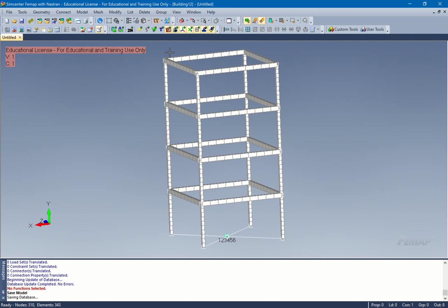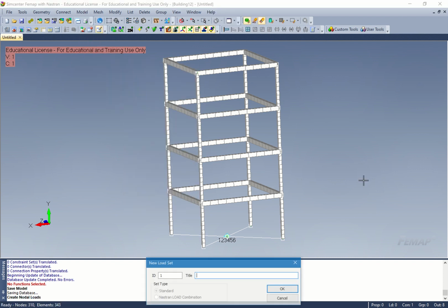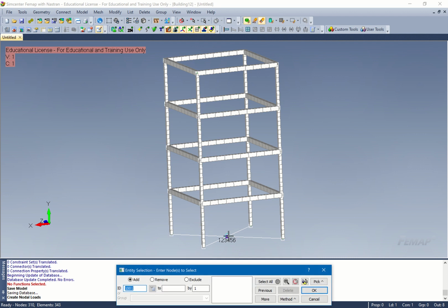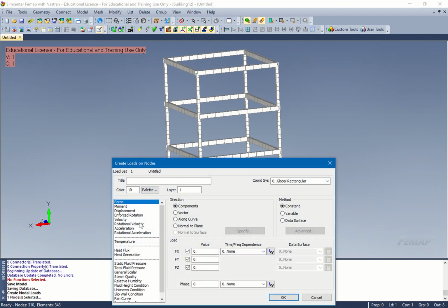So we're going to say model, load, nodal, and give it a name. Select that middle point, 1000. Perfect, that's 1000, not 1001, right? Now, this is in terms of G, which is not consistent with our model. Our model's in terms of inches, correct? The conversion from G to inches per second squared is 386.4. I copied him, so. Cool. Let's put in 386.4 for the value.